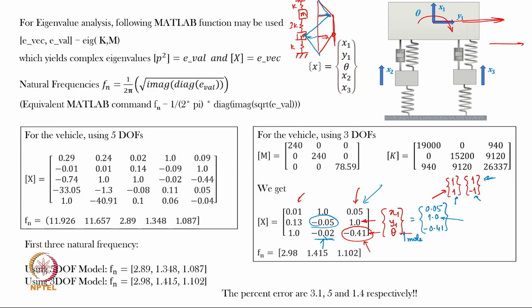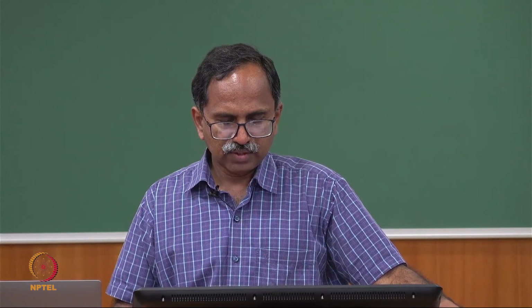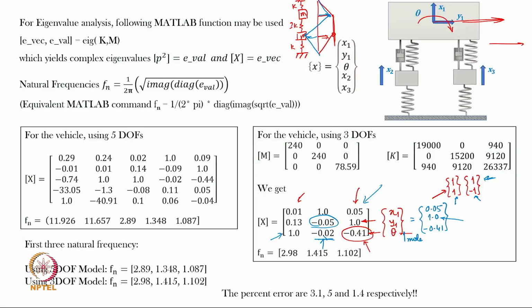That is how to read about what the mode shape represent in this case. And then of course, you can have a largely pitch motion, very little of bounce in this case. That is how you can interpret each of these mode shapes, in each of the natural frequencies. Now, please make a note that these are all shapes.